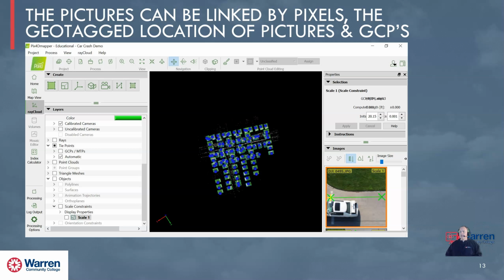But every time you take a picture with the drone, it puts the GPS coordinate on there. And here's what you need to know. GPS sensors vary in their level of accuracy, and a lot of times based on price. So a GPS processor in a Mavic or an Anafi or a Phantom, unless it's like a Phantom RTK, will be naturally inaccurate.